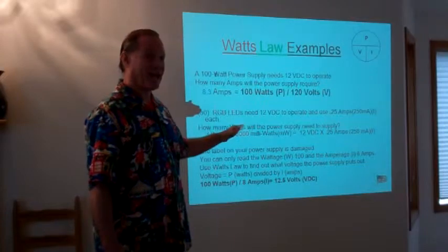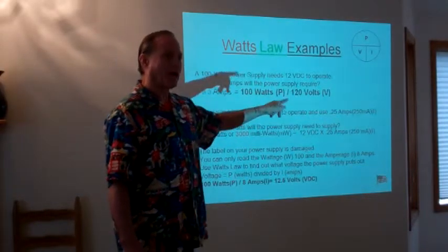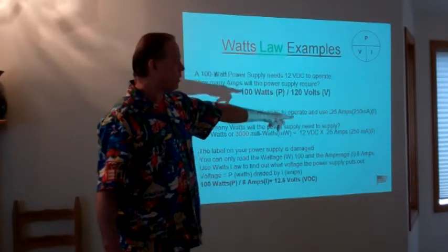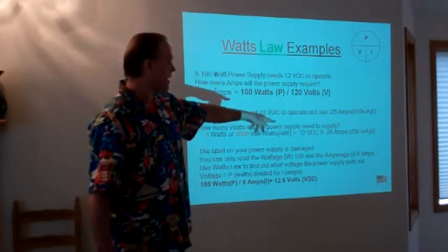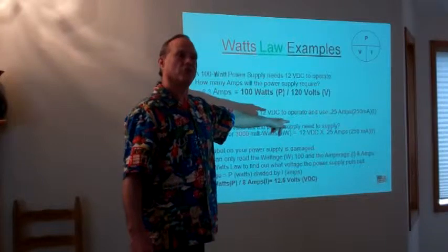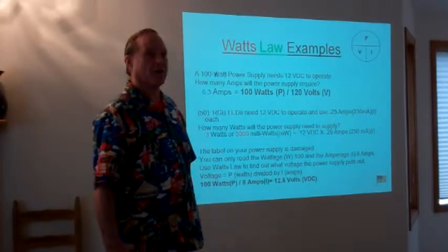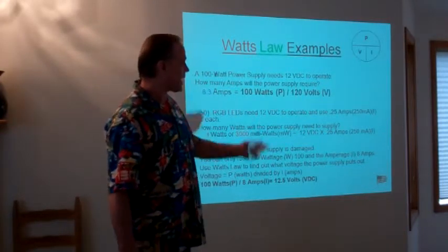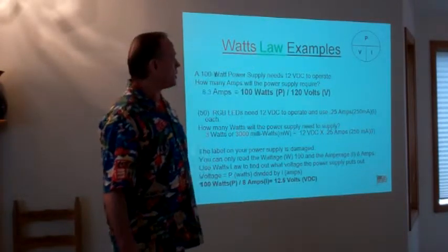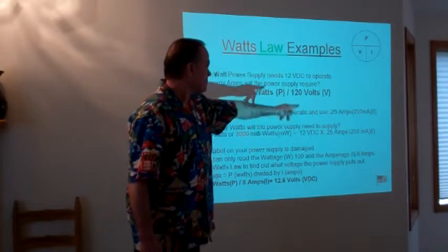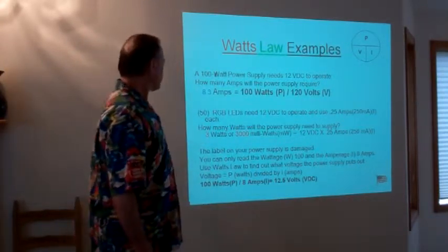So to get back to amps, you must divide that number by 1,000, because our formula will not work with milliamps in it. You have to use full amps, the full base unit for that particular thing. You'll notice I've also put I over there. That's just to identify it with our chart so you can understand that's the amps. Most of the time you'll probably see it with either A or mA on the listing.